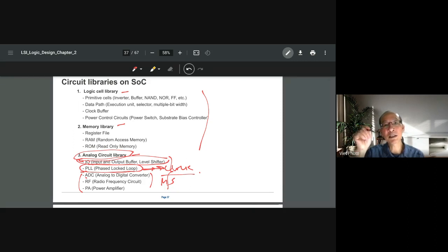And those buffers are special because they're not the same buffer as what we do here. Inside, we don't have the ESD, the electrostatic discharge. Remember, in the real world there is static electricity that can shock the circuit, so they need some IO to prevent that. So there will be protection in those IO buffers, and there's also a buffer.